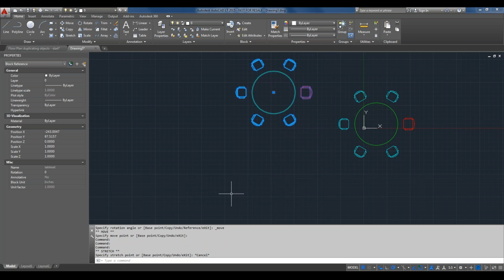So here's the thing: you're using the Windows clipboard, so it doesn't really understand it's an AutoCAD object. It will determine everything based on whatever Windows does. Using AutoCAD block insert would be better, because let's say the block is an architectural block and you're inserting it into a metric drawing, it would understand the differences.